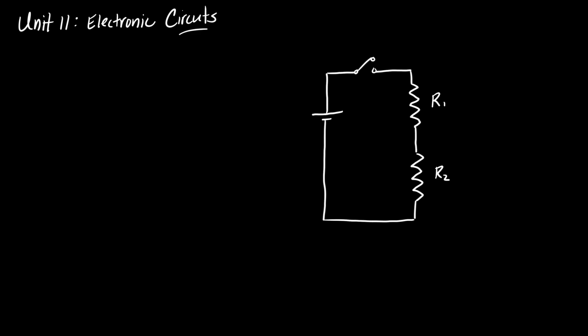Resistors are going to have a similar kind of range in that they mass produce these items. And so when they are produced, they are not perfectly the resistance that you want. Your wires will have very, very low resistance compared to the circuit elements, but you can kind of wrap up their resistance within the tolerance of the resistors that you have. For the first couple of days, we're going to treat our circuits as if they are ideal circuits, which means we have an ideal power supply or an ideal voltage source, and we have ideal resistors.